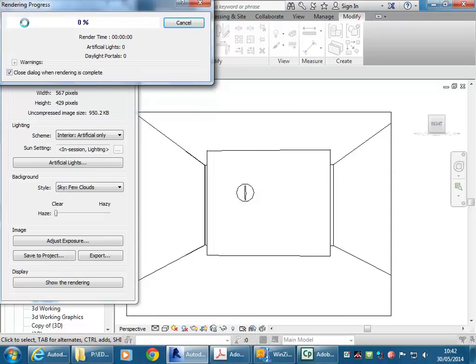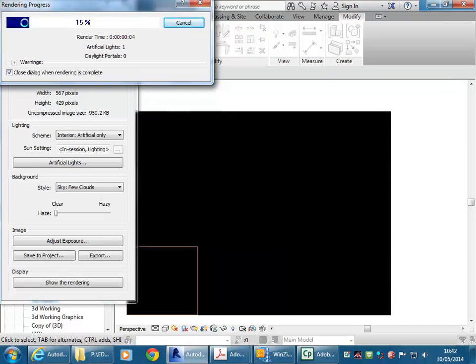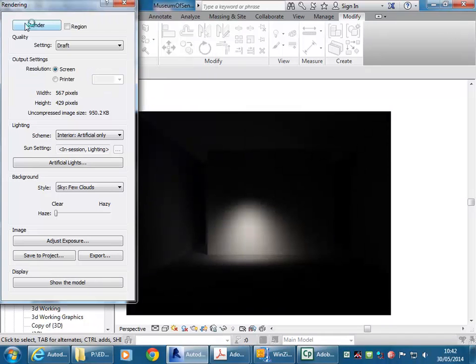Okay, so now it won't be orange. I haven't touched the walls. All I've done is change the light. And this is a natural effect you will see in the real world all the time, but your eyes compensate and often you don't notice it. But it's definitely a real effect that you have to think about, and it's fundamental to lighting design. Until you understand this, you're not really doing lighting design.